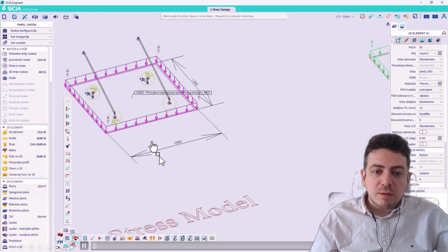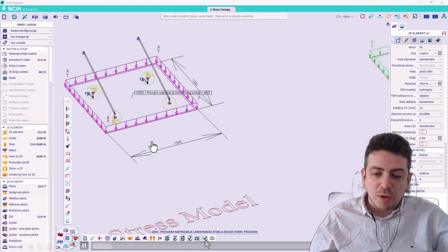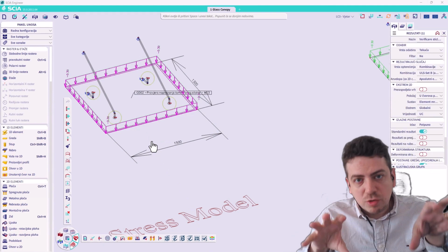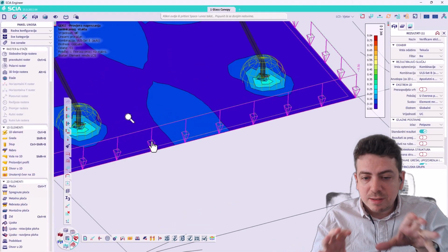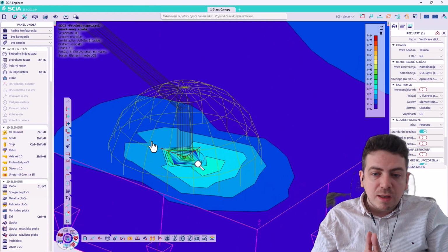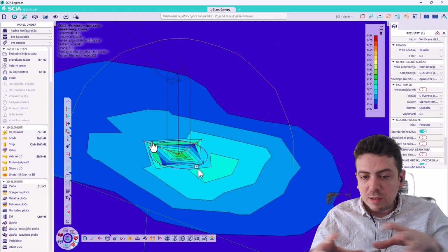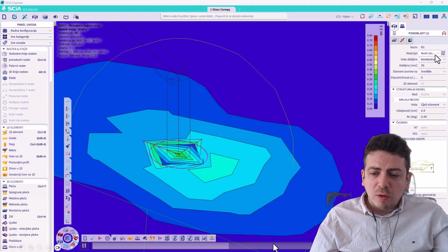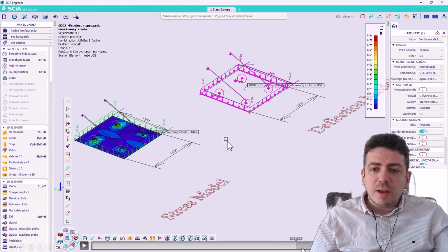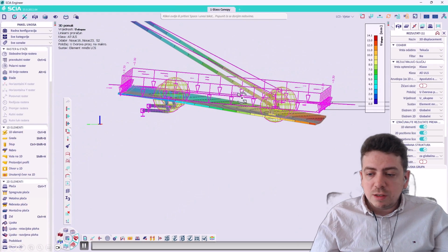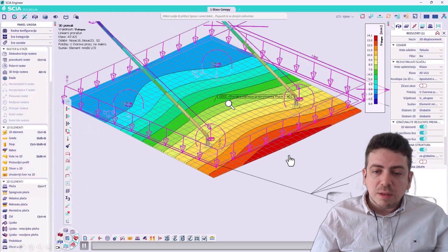And the advantage here, as you see, is that you can explore the instant geometry exactly with all the connections and see unity checks realistically in 3D, so you can identify stress concentrators, what happens around those points. And also you can study deflections on a deflection model and take into account all the connections and everything that is inside this.